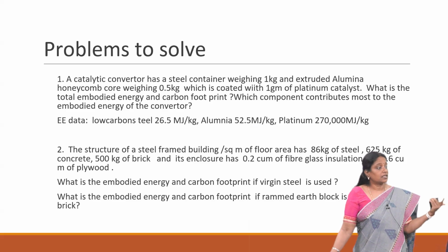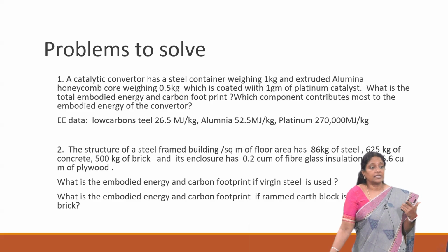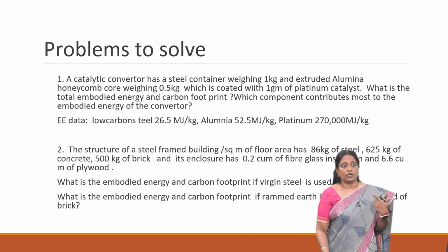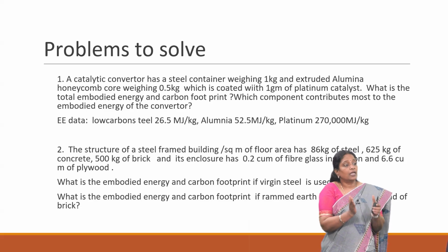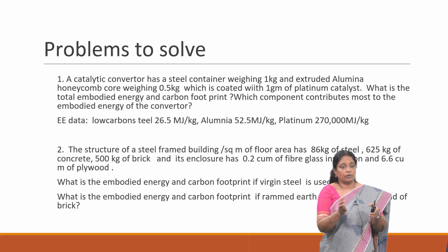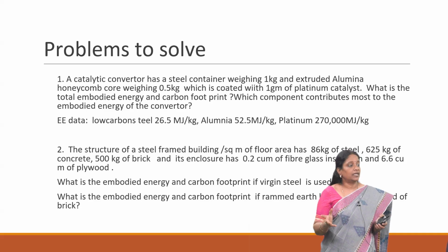I told you about plastics replacing the coal for running those high temperature incinerators, and clinkering has to happen. Lime is required, that is mined. So cement has a much higher embodied energy. Okay, concrete. Steel again has a very high embodied energy. So the more percentage of recycled materials which goes into it. Now you have numbers. If you're a builder, and your client wants a green building, this is how green you can become.